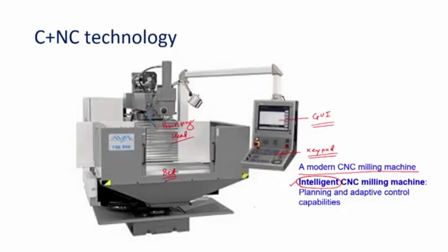Based upon the data collected from the sensors, the microprocessors of the CNC based machine tools are correcting the process parameters, and that is called adaptive control. The process parameters fed by the users are altered, changed, or fine tuned intelligently based upon the experience gained or the conditions generated during the operation.